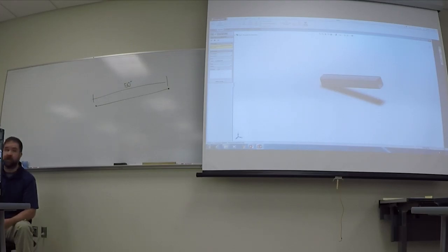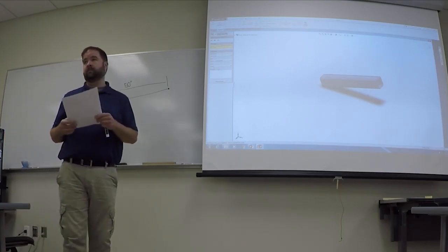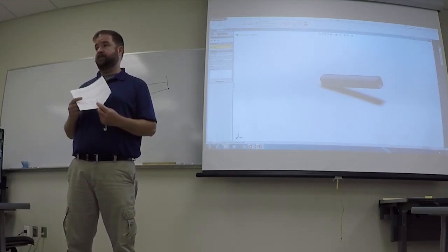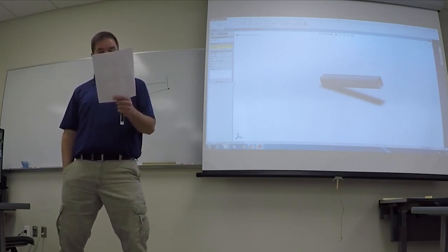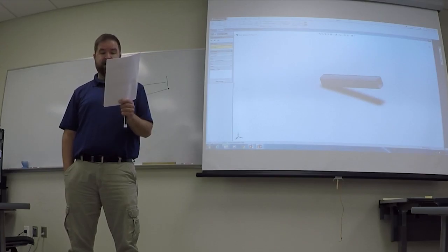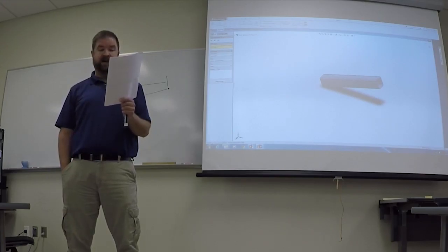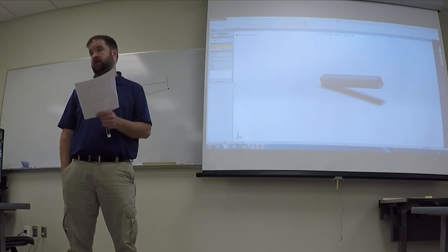Okay, so you're going to have to create the various cross-sections, and then use that to model these pieces. You're not going to find these sizes as defaults in SolidWorks. Okay? So down here at the bottom, this truss, we're going to consider the cases of the cross-section being 5 by 5, 15 by 15, and 30 by 30.